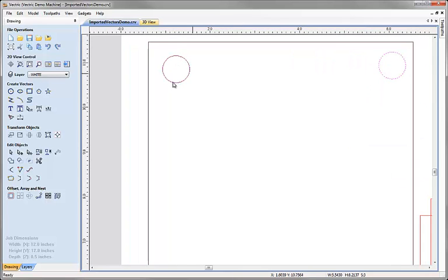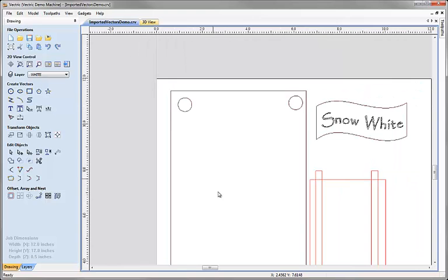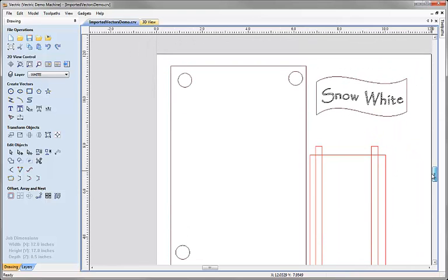And when I zoom in a little bit, you can see that what we've got is the normal selection color, the magenta selection color, over the top of a black color. And that's a really common and first indicator that we've got duplicate vectors. So what's happened here is we've got 2 circles that exactly overlie one another. And so when I select it, we're seeing the selected one in magenta dotted line over the top of the underlying exact duplicate, which is still black and selected. If I was to box select these, then in fact we wouldn't notice that because they both become selected.